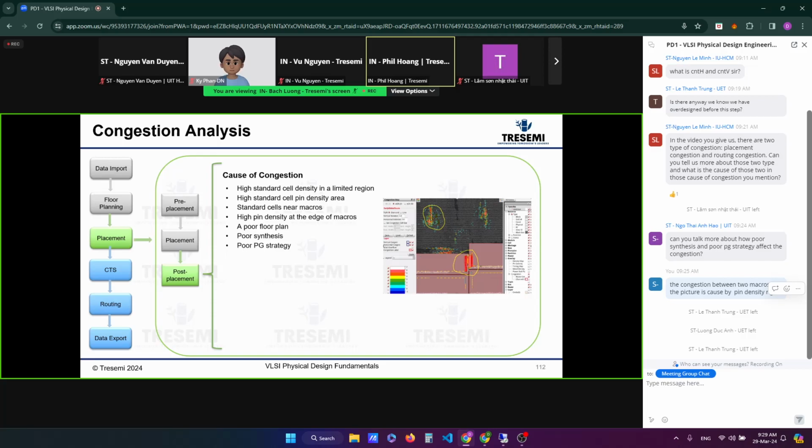So when you have a chip or a block floor plan with 70% coming in, and you're planning for 10% for clock trees and timing closure, if your design is routable, say at 80%, then that works.